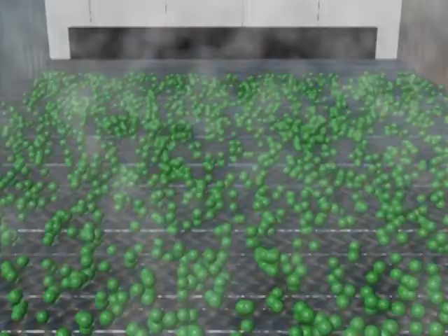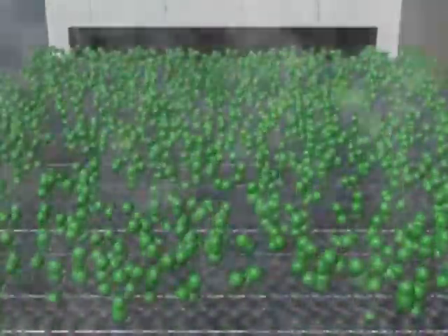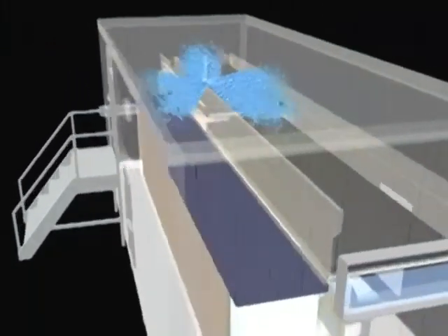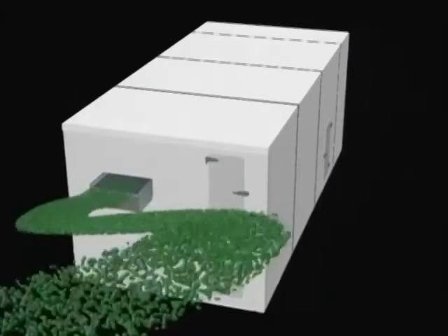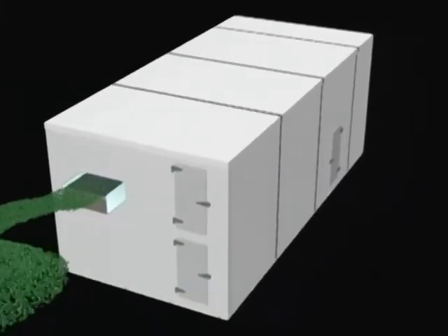The benefits are: the positive conveying design assures excellent freezing quality and reduced shrinkage loss by the continuous fluidized agitating of the product during the crust freezing and core freezing zone. The coil is shielded from the product contamination drop zone and is complete with a high-pressure washer system. Modular design allows for joining additional modular sections for future capacity expansion.